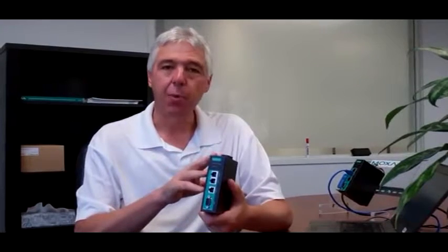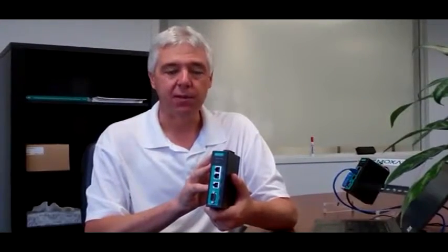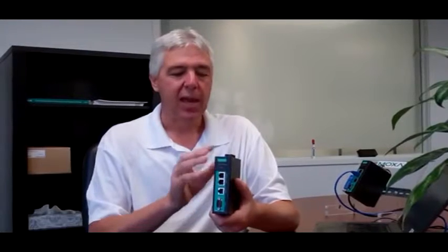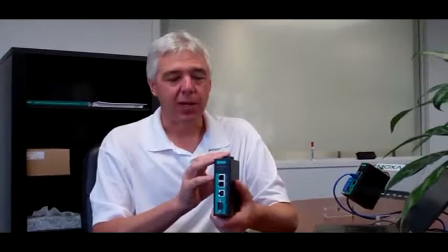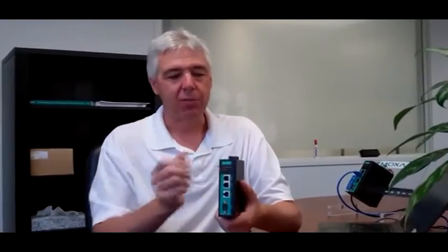The basic operation of this is to maintain an internal image of the data within your VFD. So in this Modbus connection, it's pulling data from the VFD, storing it in internal memory, and then when the request comes over EtherNetIP to grab that data, that's made available separately over Ethernet.